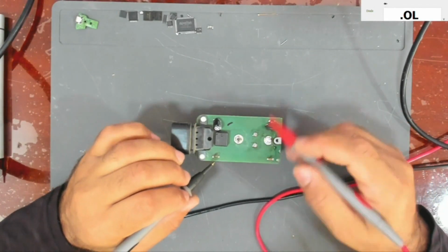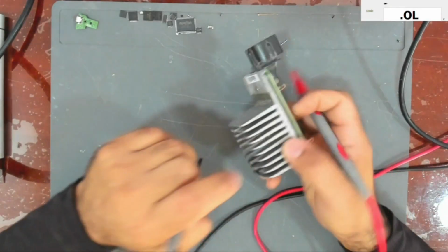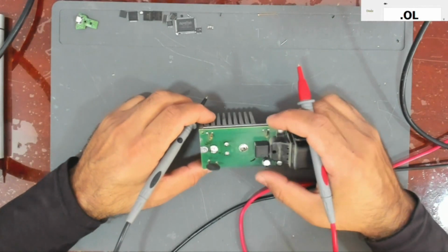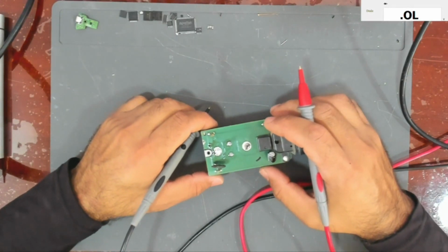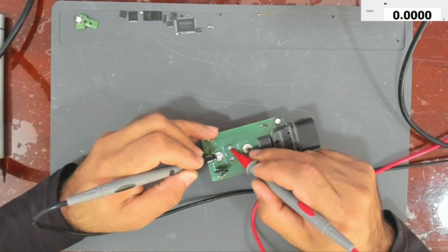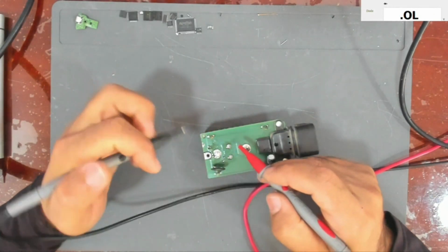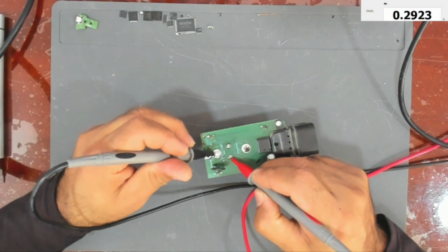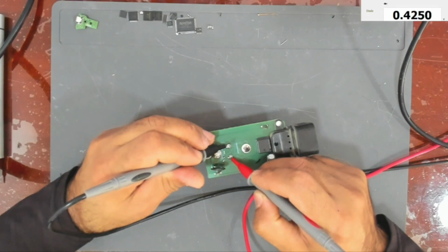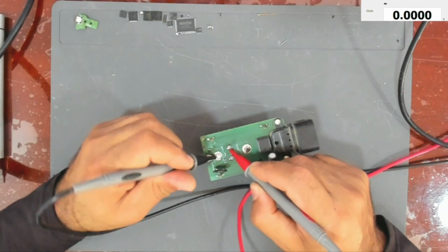And I have tested this transistor, which is this one, the big one. I have already started desoldering it, but then I realized that it's not recording anymore. Don't know what has happened. So I found this transistor is shorted. Collector to emitter is shorted. Base is good. If we check base to collector, base to emitter, it's not shorted, but the collector and emitter are shorted.